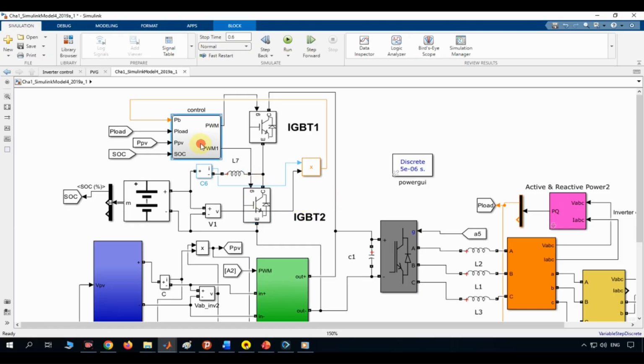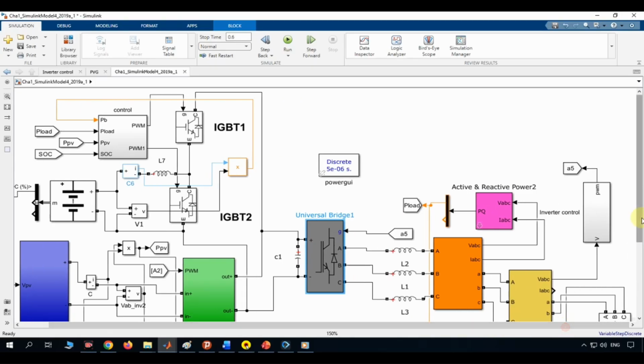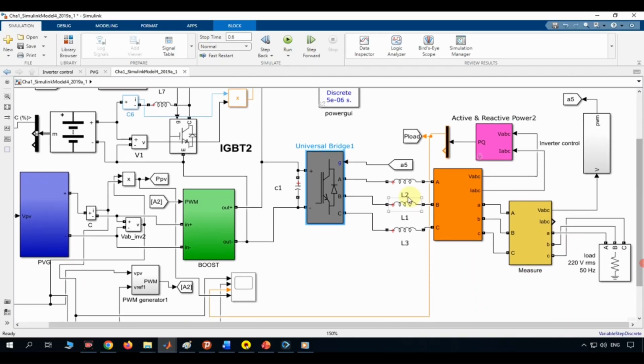By this point, both the solar side and the battery side have contributed to a single shared DC bus. This gray bridge is where that DC power finally becomes AC. It's a three-phase switching bridge, and its gating signals are what actually shape the output into a usable waveform, based on the modulation index and voltage command coming from the inverter's own controller.